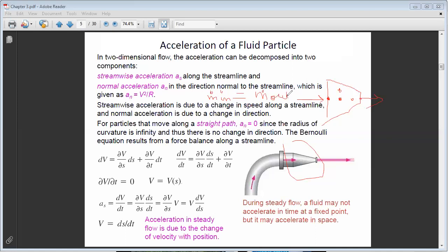And you know the expression of a mass flow rate? The mass flow rate can be written as density times area times velocity. Since it's an incompressible flow, I will write rho A1 V1. This is section 1, this is section 2. So rho A1 V1 is equal to rho A2 V2.